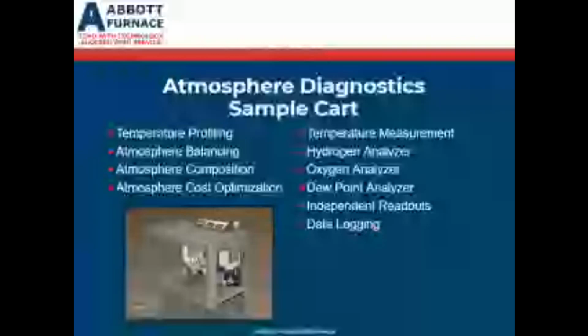Again, there are the things we can do with monitoring the atmosphere, and the copper steel test to determine if we have an air leak or a water leak. There are some other tools we use, like combustible gas sniffers. We'll come in and run those around the flanges or the side covers where there are gaskets.